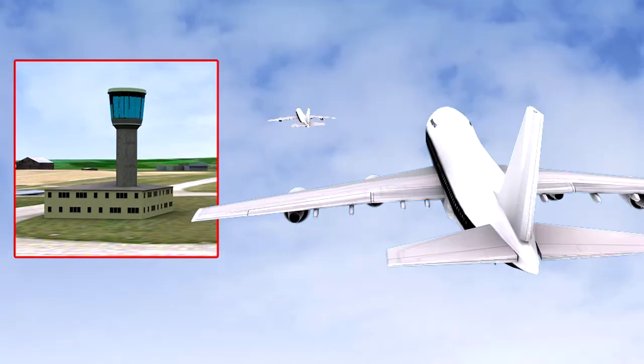Essential air traffic is defined as that controlled traffic to which separation is applicable, but in relation to other controlled flights is not or will not be separated by the required minimum. Essential traffic information is passed to all controlled flights when they constitute essential traffic to each other.